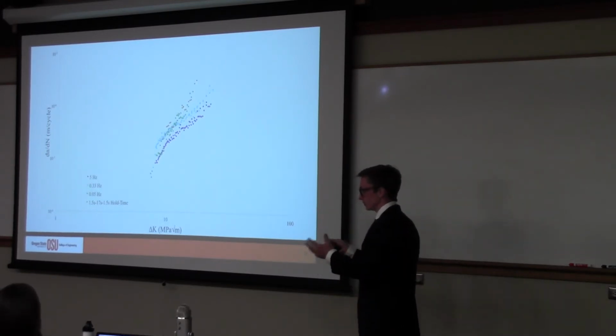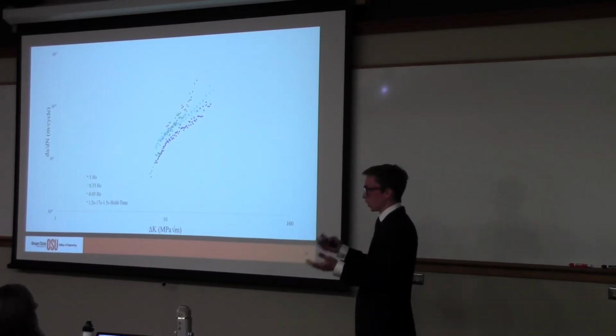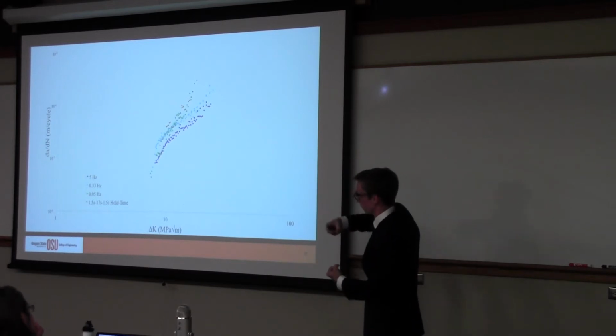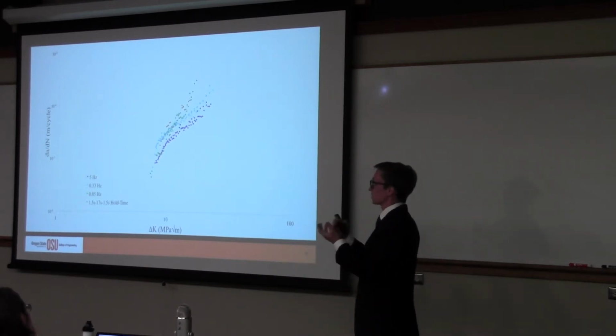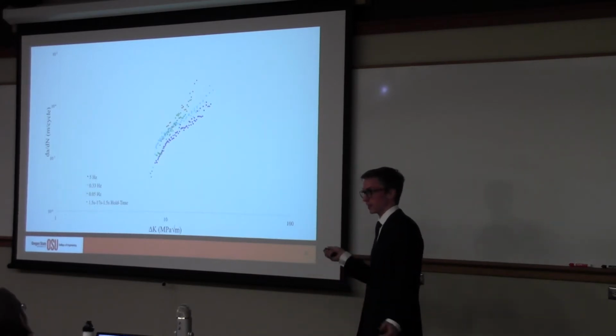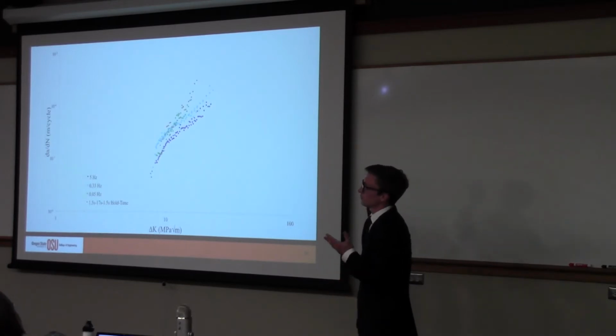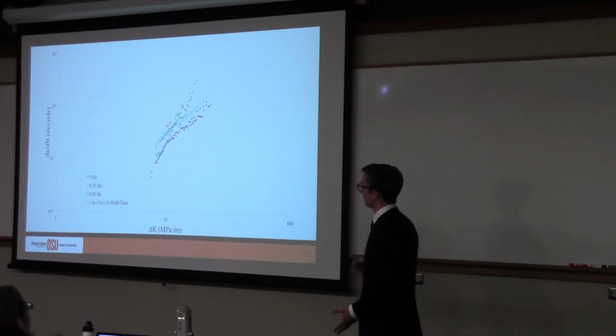Pmax, when you get the geometry of your sample, translates into a Kmax. And Pmin, the load minimum that you're applying in your waveform as you go up and down, translates to a Kmin. And so Kmax minus Kmin is delta K. And this is traditionally how you're going to view the crack growth data.